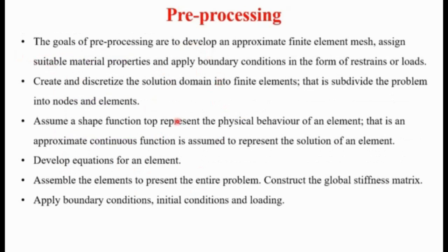The goals of the pre-processing are to develop an approximate finite element mesh, assign some suitable material properties, and apply boundary conditions in the form of restraints or loads. The boundary conditions are in the form of these restraints, constraints, and loads that need to be applied. So in this pre-processing stage, it creates and discretizes the solution domain into finite elements.